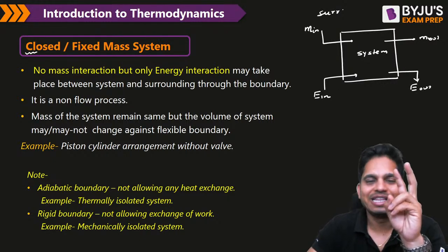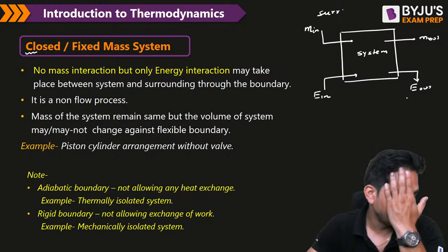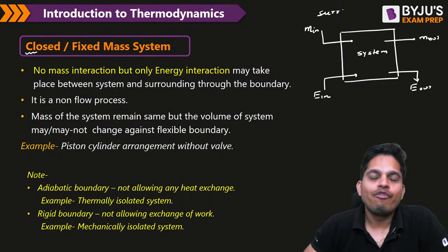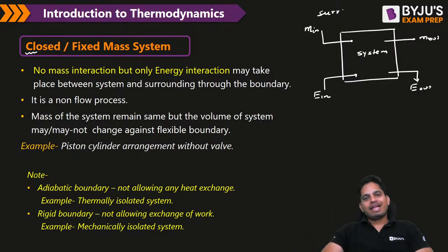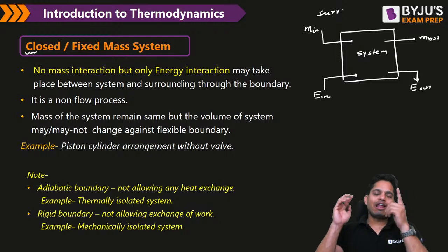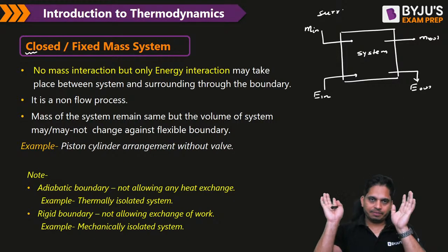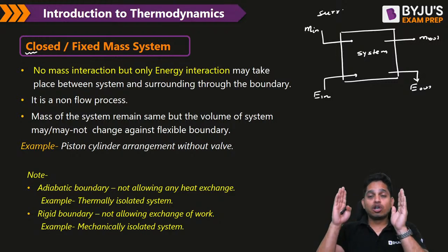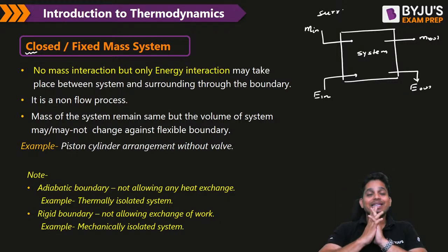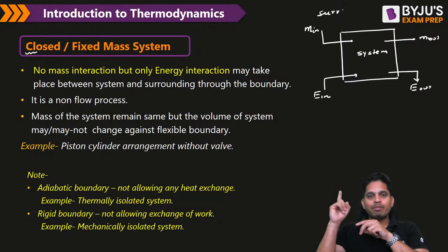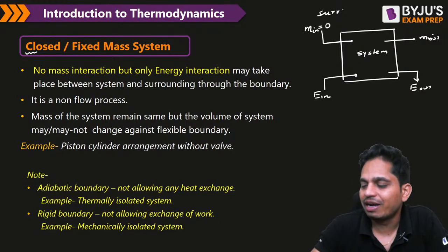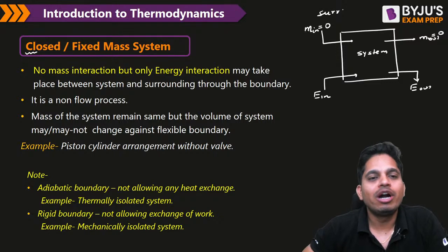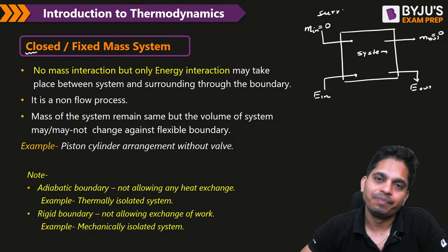So either in mass form or energy form it can interact. Now when I am saying closed, earlier this room is my system, and in general I can allow mass or energy transfer. But I am saying closed. That means I have closed my system to one of the interactions. And what is that? Mass transfer. You will not allow any mass to enter or exit.